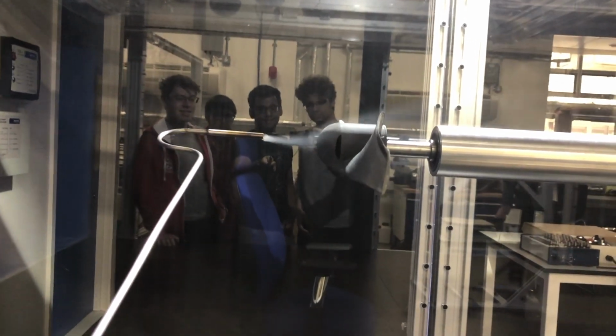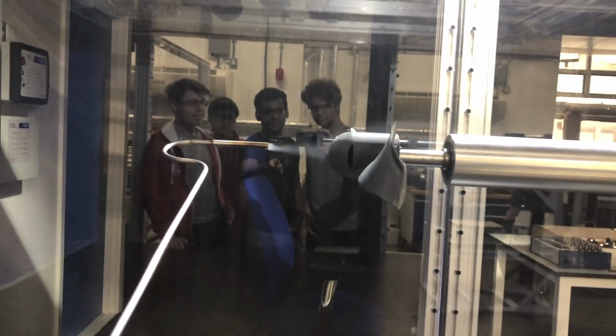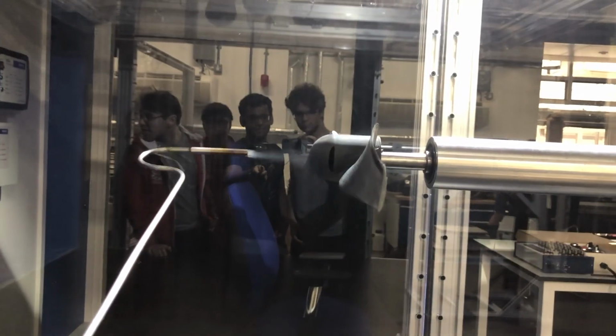What? To understand what was going on, we used a smoke streamline generator to visualize the airflow around the nose cone. As you can see from the footage, the channels did not perform as intended and no airflow was directed towards the blades. We think that this was because the channel was too small and not enough airflow was passing through the channels for the smoke to be visible.